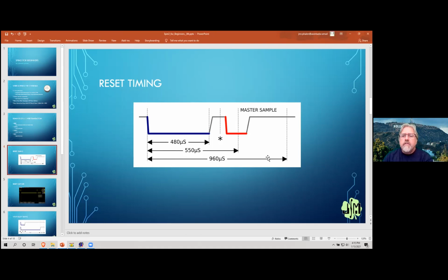So the things I just covered are what you'll see in the normal documentation for one-wire stuff. But you notice there's another line right here with an asterisk. This is one of those insider tricks that the Dallas engineers told me about. You see, what if you don't have a pull-up on your bus? Now, in our code, we're using a software-based pull-up, but what if you had a hardware-based pull-up and you forgot to put the resistor in?